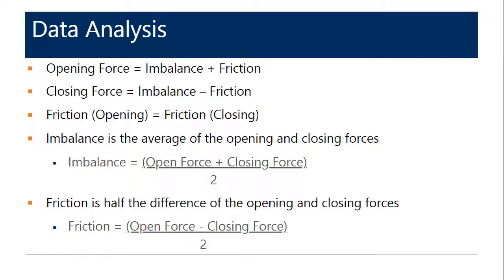Okay, our next question. How do you compensate for environmental conditions like wind or ice when determining the span balance? The gauges are not intelligent, so they don't know if the load that they're seeing is from the imbalance or if it's from wind acting on the bridge, or if you have a vertical lift bridge and there's equipment on the bridge. So it's important to perform testing when there are no other external loads acting on the bridge.